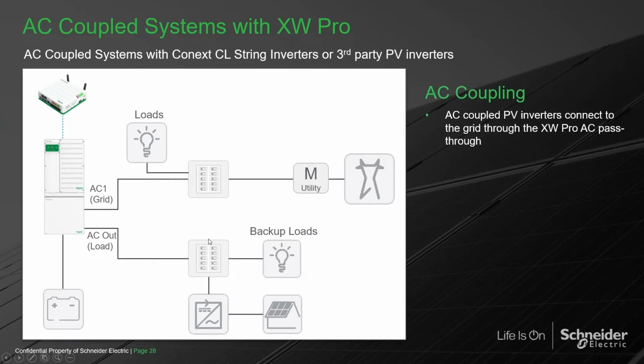So that's the difference between DC, which is connected to a charge controller, which is a DC to DC device, to this architecture where the array is connected to a grid tie inverter, which is a DC to AC device. And this is why this architecture is called AC coupling. What happens here? This customer has a net metering agreement, is connected to the grid.